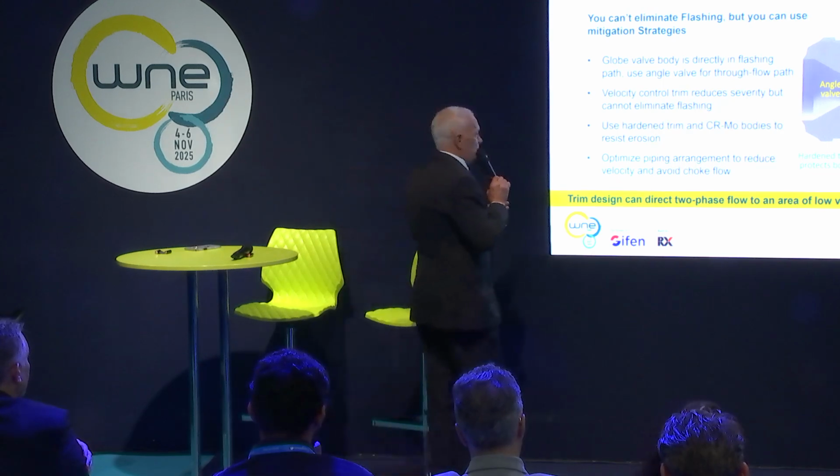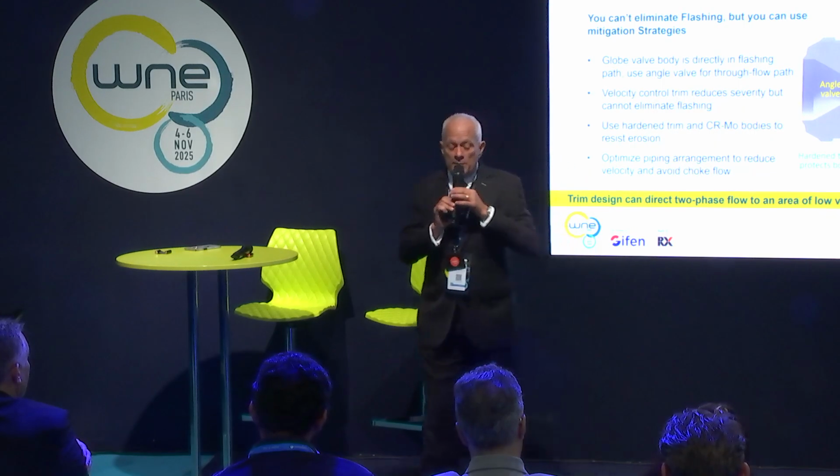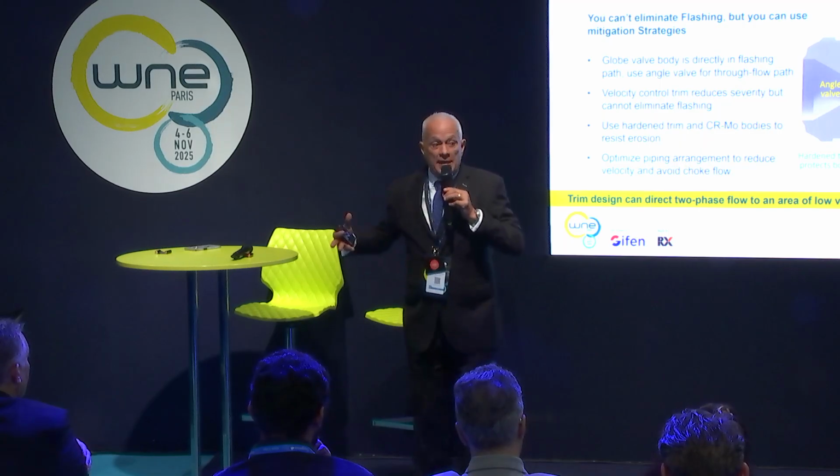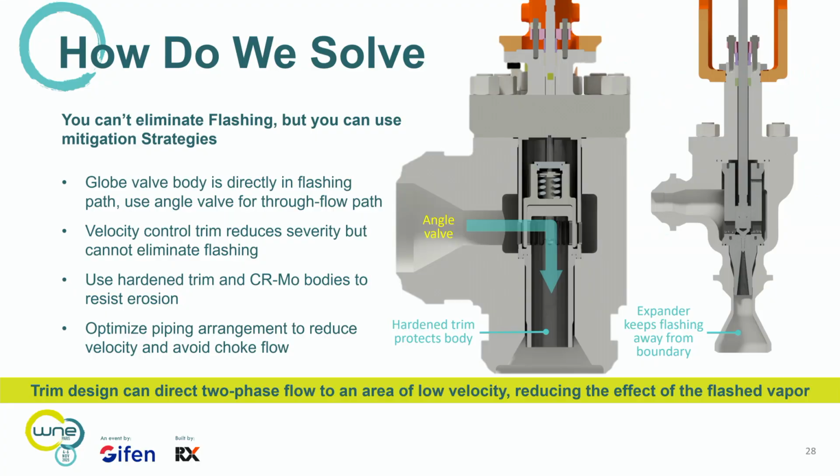So the other thing, when you're turning from liquid to two-phase flow, remember, as a liquid turns into gas, it's expanding. Okay, where's that expansion going? If you don't have a larger outlet on the valve, then basically you're choking the flow. When you start choking the flow, you have a problem controlling that whole system because it's just clogged up there.